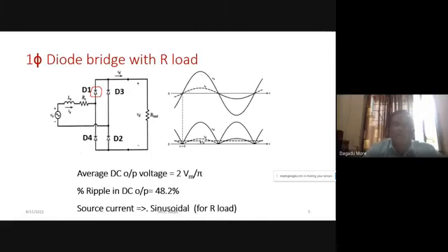And now let us consider the positive half cycle of the supply. So this is our supply, a positive half cycle of supply. Which devices will be forward biased here? The upper terminal is positive. Let us assume this is positive, this is negative. So we say here D1 and D2 will be forward biased. Is it right? In the positive half cycle, devices D1 and D2 will be forward biased.